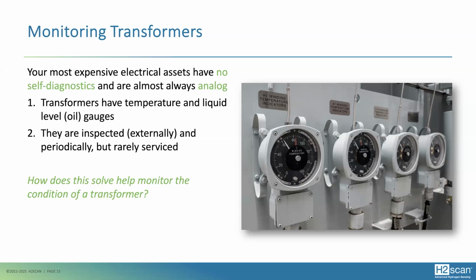We'll see some temperature gauges. Yes, they may be digitized, but only with the intent of feeding a cooling system, or more than likely SCADA and protection relaying. Transformers are inspected, usually externally, but if you're in that industrial realm where you take your annual outage and do some dielectric strength testing or DGAs, it's partially internal, and perhaps every 4 years you're doing a full electric test suite.